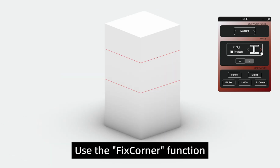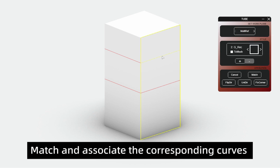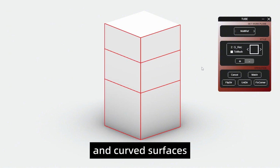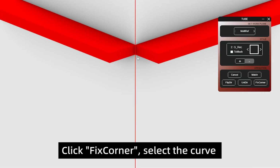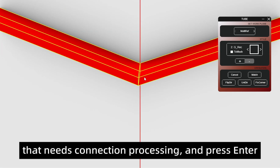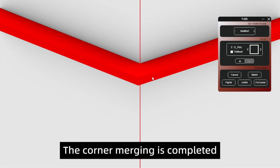Use the Fix Corner function to handle the connections of rods. Match and associate the corresponding curves and curved surfaces. Select curves to generate solids. Click Fix Corner, select the curve that needs connection processing, and press Enter. The corner merging is completed.